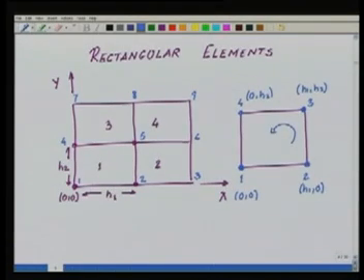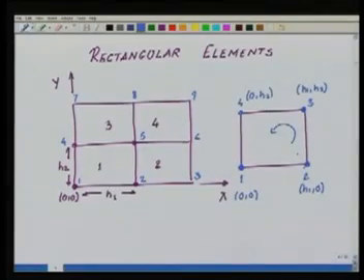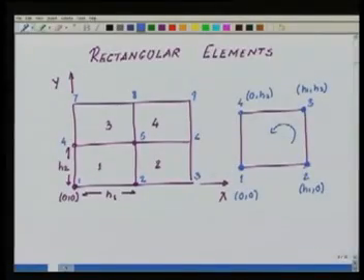So what is the simplest basis functions that we can define, or simplest element shape functions? They have to be defined with respect to these 4 vertices. Okay. So those shape functions, if I define now, how am I going to do that definition? So the definition is very simple. Let's now take this element apart, because these angles are 90 degrees. So let's imagine I have taken these two edges apart, this edge and this edge. Let's say this edge with the nodes 1 and 2 and this edge is with the nodes 1 and 4.